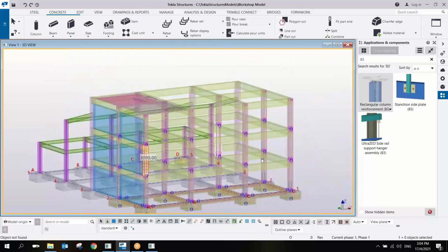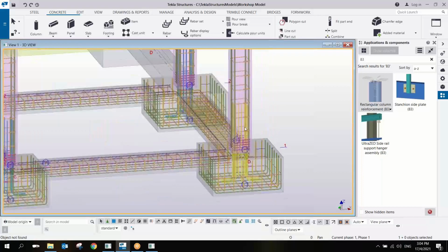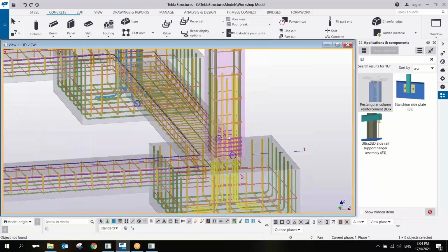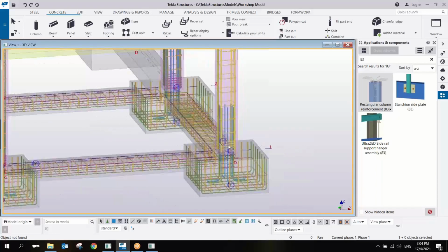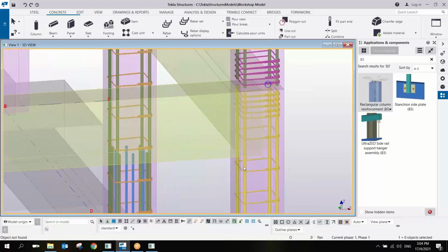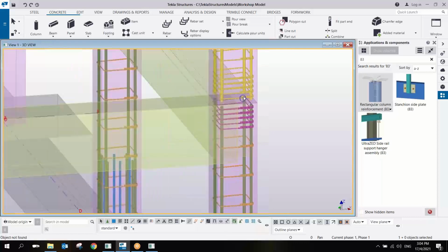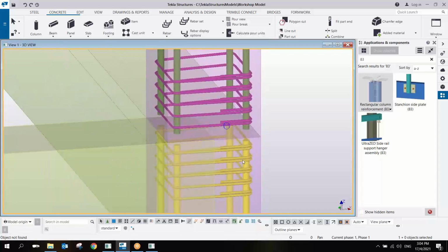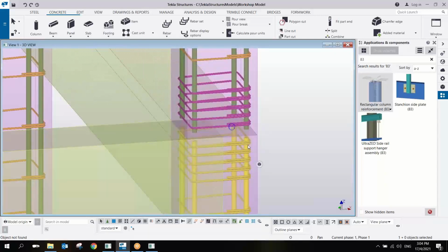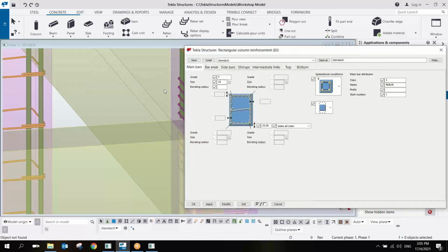And then for the connection between the beam and the column, okay. Now, if you notice, this connection is something like a cast in place connection. So meaning cast in site. But in case that this one is a precast connection, the column and the beam, it will have a corbel connection. But before that, here, if you want to have this column with the cranking, and then extend the reinforcement to the other level of the column.